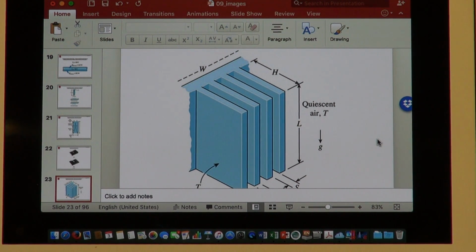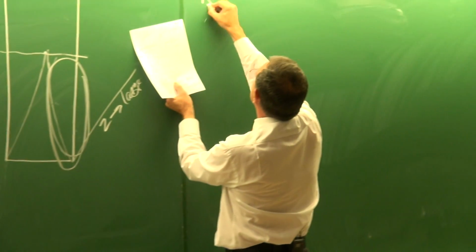So it has become a huge problem. But in general, this is also an application of a flat plate. You agree? But it now depends on the length L. If the length becomes very large, then a significant part might be fully developed. So again, it depends on the length. If you look in the textbook, you will see that there are many equations available, and again, they are divided into the constant wall temperature cases and the constant heat flux cases. So, for example, for the case where Ts is a constant,